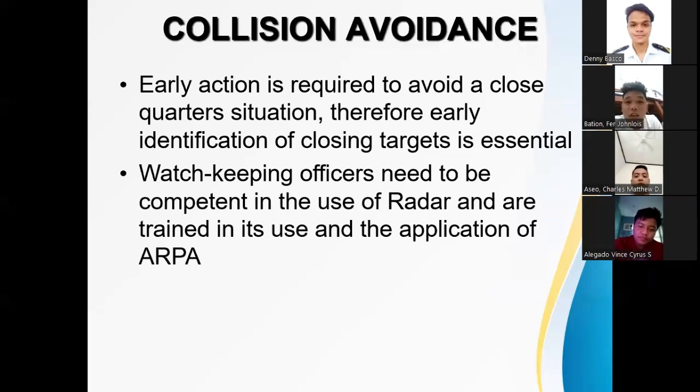Good afternoon, everyone. I am Cadet Pution. On collision avoidance: early action is required to avoid a close quarters situation. Therefore, early identification of closing targets is essential. Watchkeeping officers need to be competent in the use of radar and trained in its use and the application of ARPA. Next slide, please.